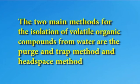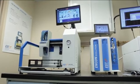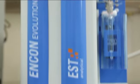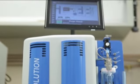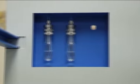Let us come to the third aspect, volatile organic compounds. The two main methods for the isolation of volatile organic compounds from water are the purge and trap method and the headspace method. Purge and trap method: this method, also known as the dynamic headspace method, removes volatile compounds from the sample matrix by passing an inert gas such as helium or nitrogen through the matrix. The target volatile compounds are desorbed from the aqueous phase to the gas phase and are then separated from the stream of gas by adsorbent filters.